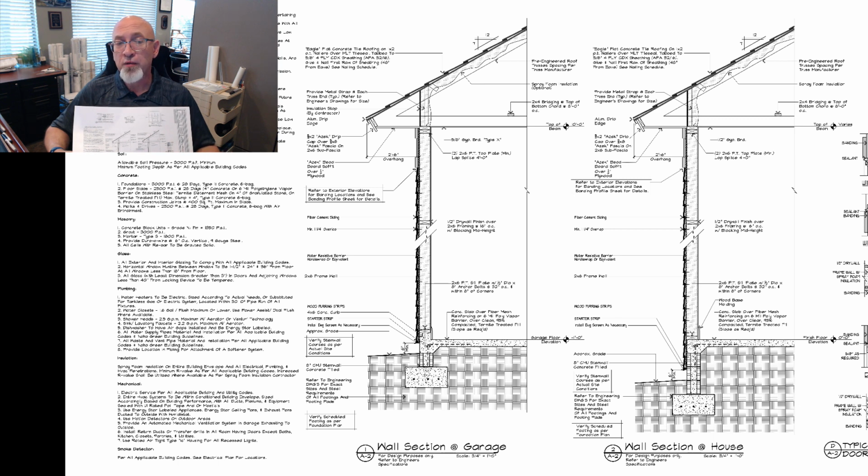It's so important that you work with a local engineer to look at your soil conditions there. Obviously, you might have some in northern climate. You're going to have some frost conditions, so the foundation would have to go deeper to be below the frost line. There's so many different parameters. Obviously, with Florida, we have to worry about tie downs and wind uplift, things like that. Which again, we can't design for every scenario.